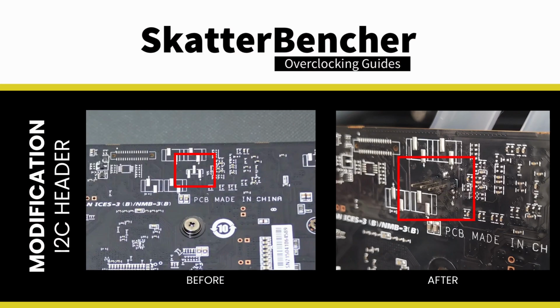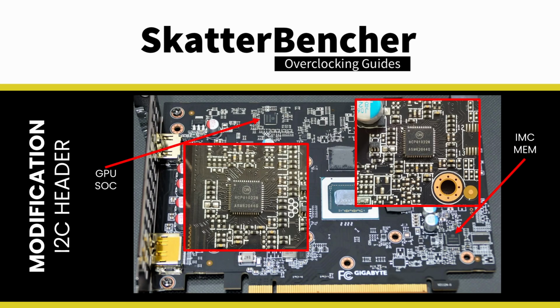This modification adds an I2C pin header on the graphics card PCB, allowing us to communicate with the onboard ON Semiconductor NCP81022 digital voltage controllers. We can then connect the EVC2SX device to the I2C pins and easily control the behavior of the voltage controllers. I will focus only on the voltage controller providing the GPU voltage and SoC voltage. The other voltage controller offers the voltage for the memory controller and the memory. I focus exclusively on the GPU voltage controller because that's where I obtain the only tangible performance benefit.